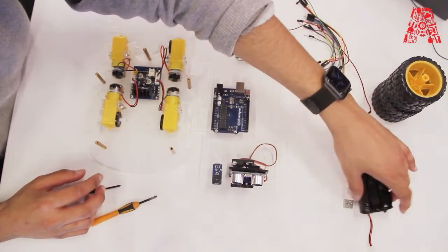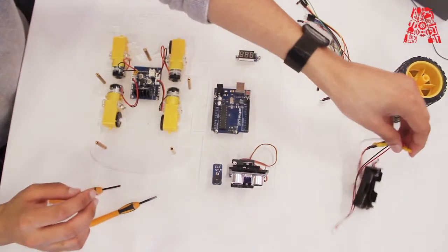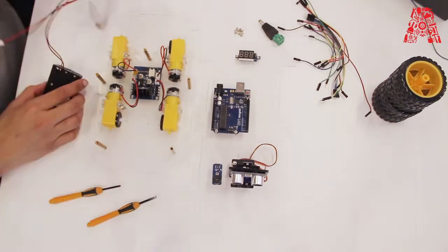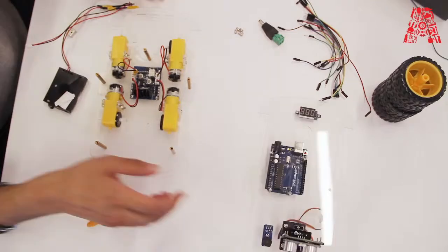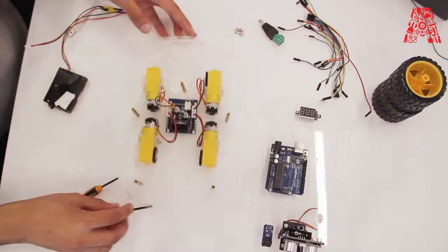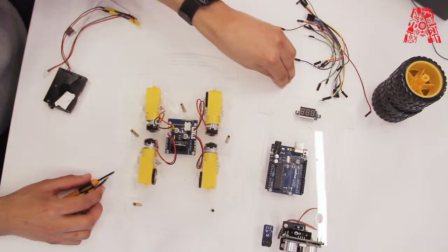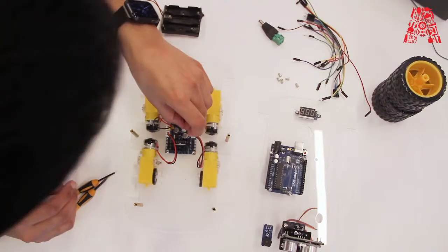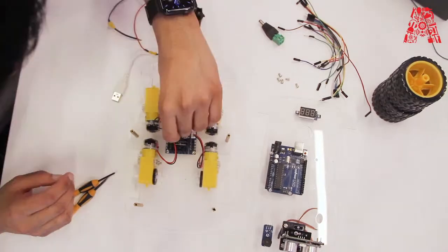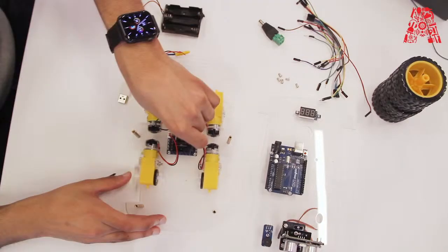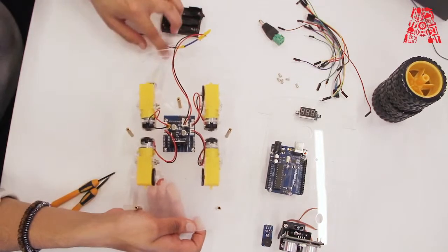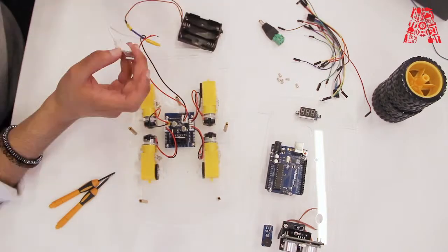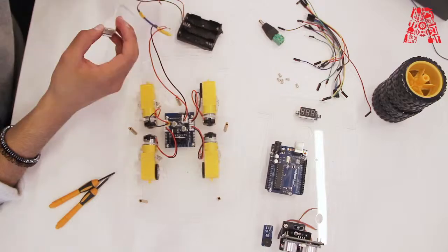Now we need to connect the power supply. You just need to give the car a voltage of more than 7.2 volts, otherwise the car will not work. So this wire, you would just put it over here into the ground of the motor driver, right over here. So we are going to connect a power bank and 3 batteries in series to generate a voltage of more than 7.2 volts.